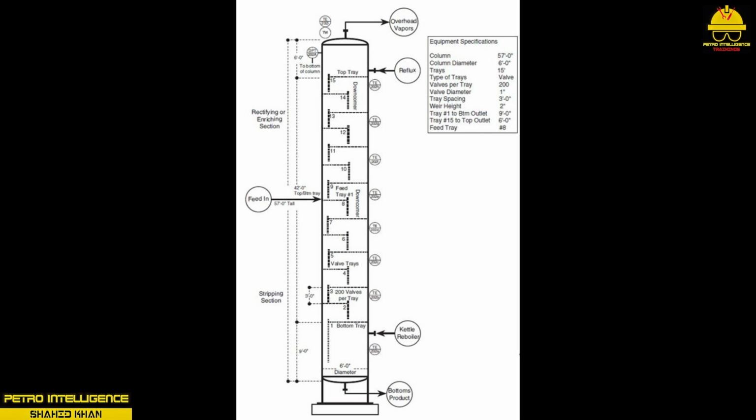A different molecular structure can be found on each tray, in the bottom of the column, and in the overhead accumulator. The initial feed temperature is carefully controlled as the product enters the column, for example 180 degrees Fahrenheit. Typically, a higher temperature exists and is controlled at the bottom of the column than at the top, giving the tower a unique temperature gradient, for example, 160 degrees Fahrenheit top temperature, 222 degrees Fahrenheit bottom temperature.